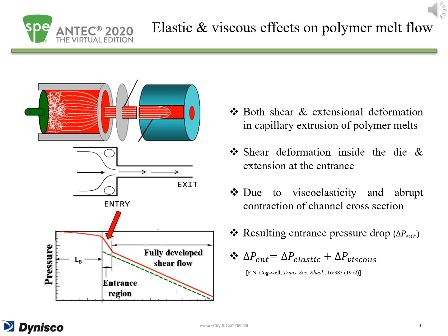Consequently, large elastic deformation energies are produced, either dissipated or stored in the melt, leading to an obvious entrance pressure drop. It is believed that pressure drop at the entrance flow consists of two components: elastic pressure drop due to a stored elastic extension strain energy, and viscous pressure drop due to viscous dissipation.